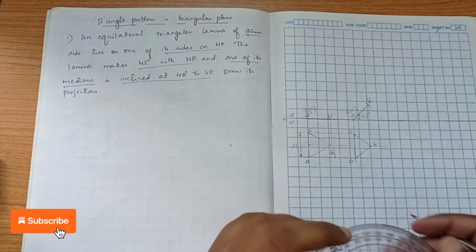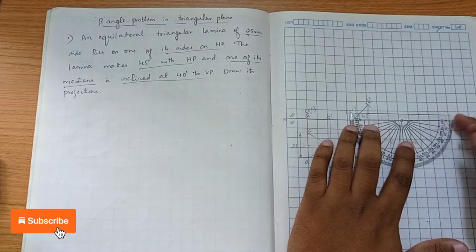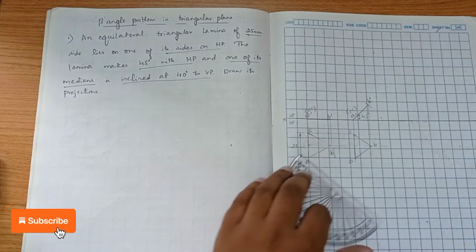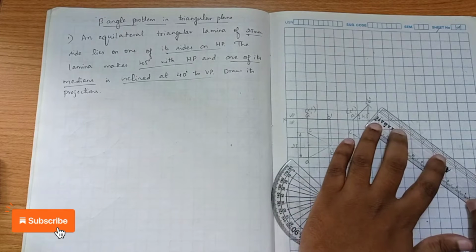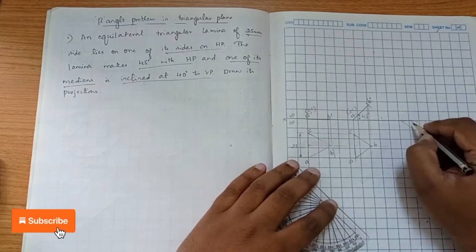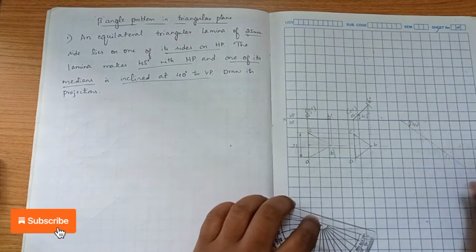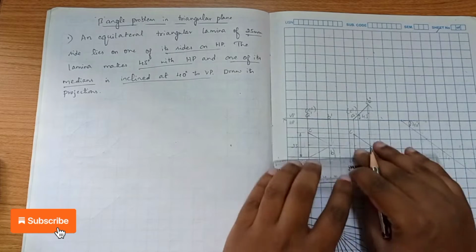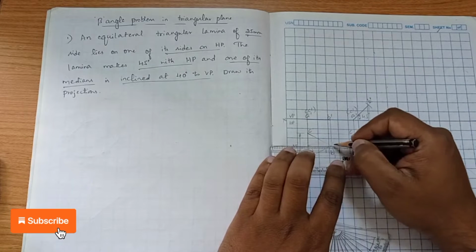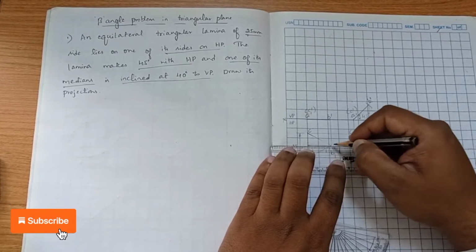First I mark a reference point, and then at this reference point I mark 40 degrees, because the angle of inclination to VP is 40 degrees. So I draw an angle line here with an inclination of 40. After drawing the angle of inclination, we have to draw the medians. The median length starts from this point to here, a horizontal line.